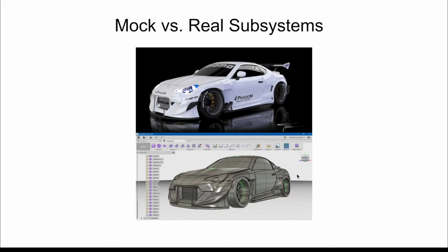And in our configuration file, we would specify for each particular robot that one robot has a real shooter and it would construct a real shooter with all the necessary actuators that the shooter has. And on the other robot, we would say it does not have a shooter, so it would create a mock shooter which wouldn't need to construct any actuators. And this allows us to be very modular with our code and allows us to run the same code on different robots with different capabilities and easily and dynamically change those capabilities in our code. So basically this is the analog of what we had for sensors in the last video.